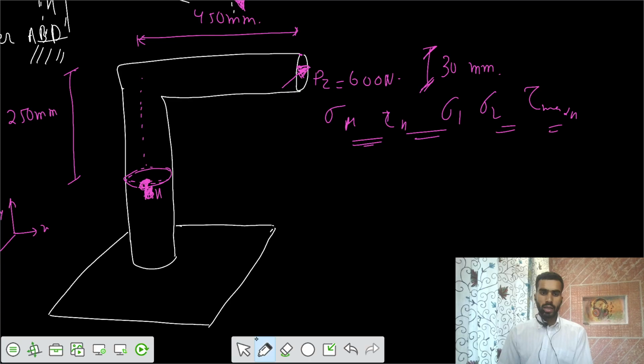Now we want to say whether there is any other force that gets transferred. Now see, this is load in the Z direction, and on this point, this load is actually in this way across, so the same would get transferred here. If I have this shear here, on this section there would be an upwards shear, and if that gets transferred to this part, it looks like a shear on this top, and here it would be upwards.